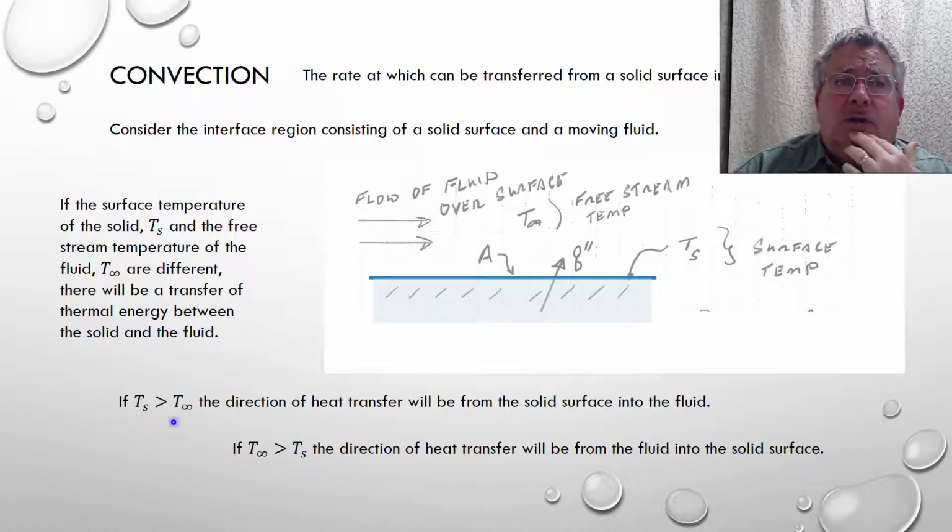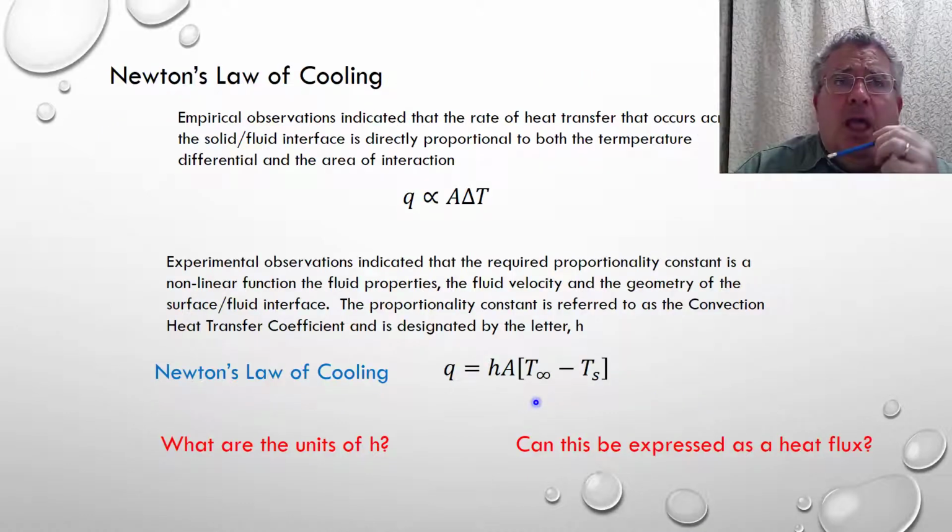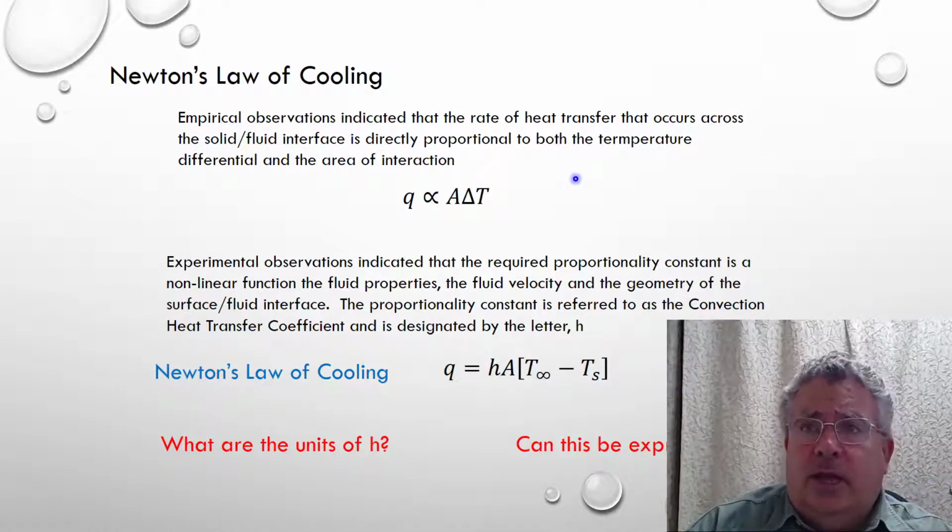Just stating it officially here, in words: if TS, the temperature of the surface, is greater than T infinity, the direction of heat transfer will be from the solid surface into the fluid. And if the free stream temperature out here is greater than the surface temperature of the solid, then we will have transfer into the surface. And the law that relates this is referred to as Newton's law of cooling.